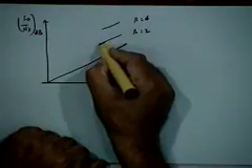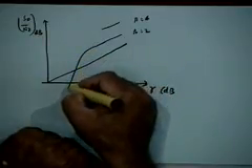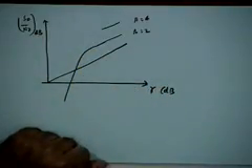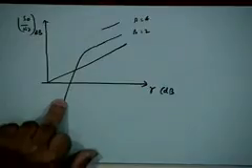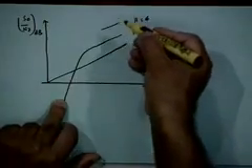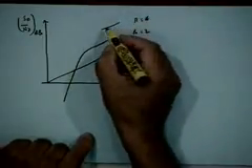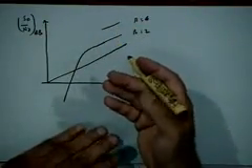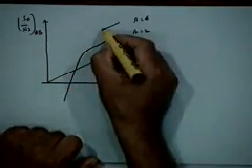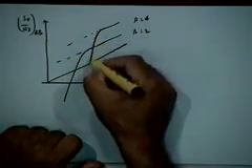Now, taking into account this threshold effect, the actual curves, instead of going like that, go something like that. That's the threshold effect. So at this point, you start deviating from the straight line curve very significantly, right? And as you increase the value of beta, it's very interesting. I'm not proving all this. As you increase the value of beta, this threshold becomes more and more significant, right? This will occur much earlier than it occurred in the case of a smaller bandwidth signal. So instead of going like this, it will go like that now.